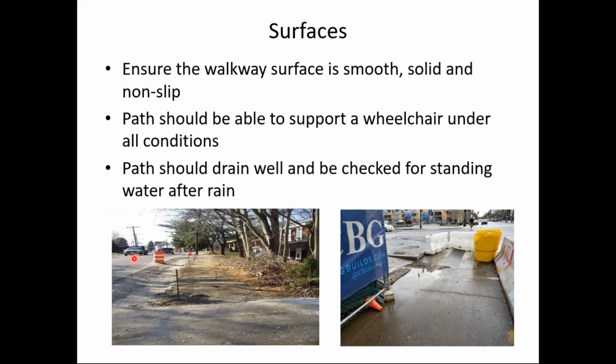Surfaces, I think we talked about that a little bit yesterday too, but it bears repeating and discussing that today. The walkway surfaces must be smooth, stable, and slip resistant. The path should be able to support a wheelchair under all conditions. Notice the photo on the left. Someone sent me this a few years ago and claimed that this was an accessible temporary route for their project. And I responded that no, it's not.